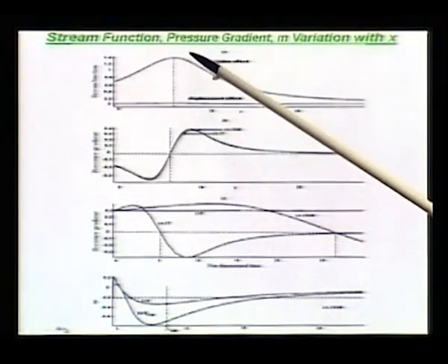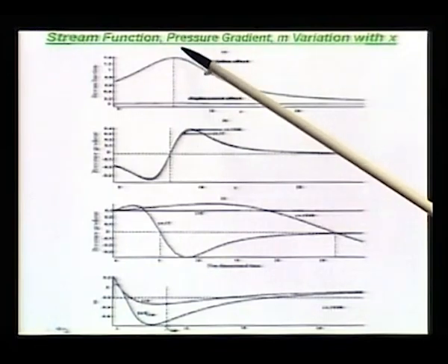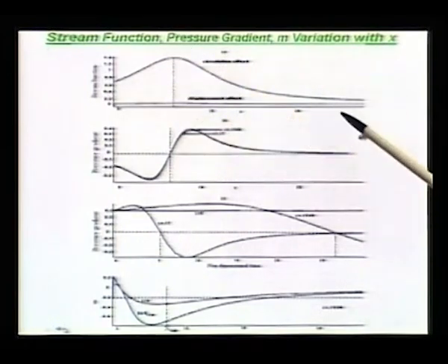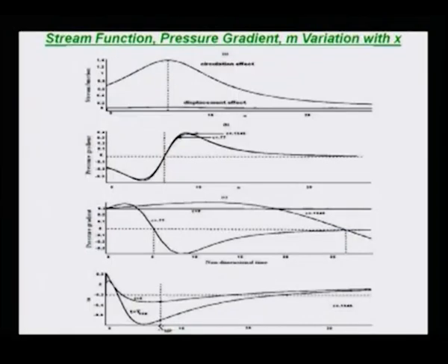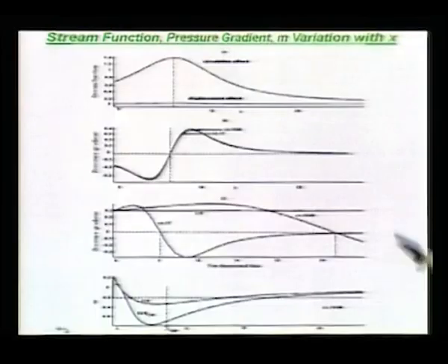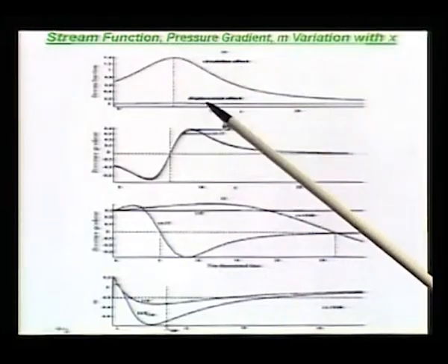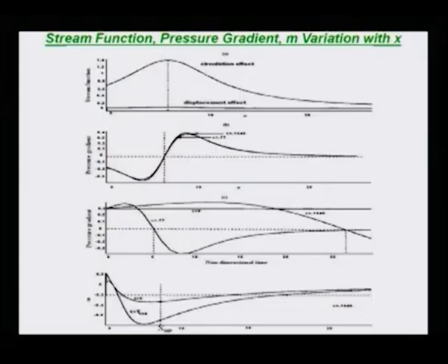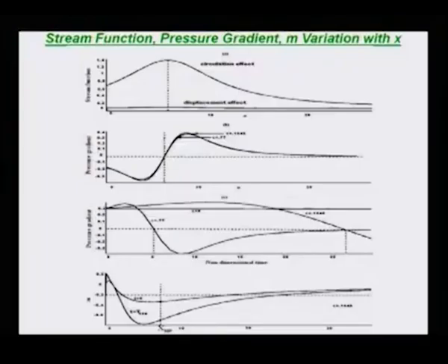Of course, the disturbance is maximum in the vicinity of the cylinder and it falls off, and this is due to the circulation effect, the gamma part. If I parameterize the value of gamma and work out an expression, this is how that circulatory effect would be. However, the displacement effect remains flat. It remains the same for all x's. That is what you are seeing.